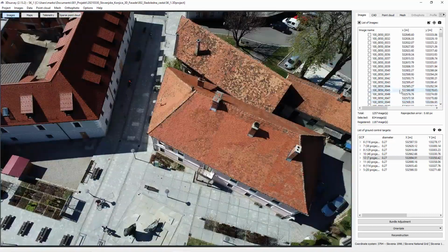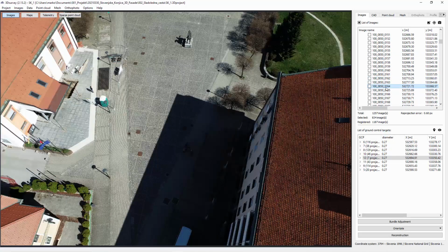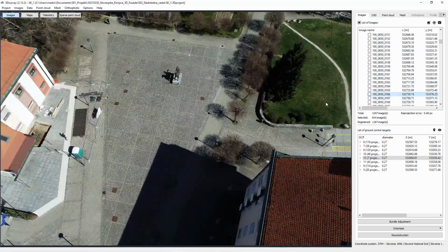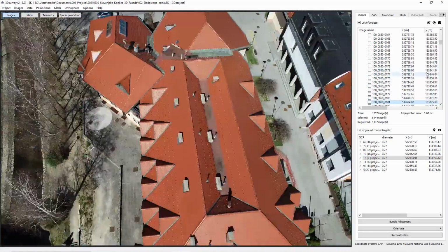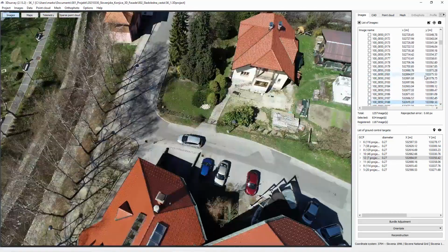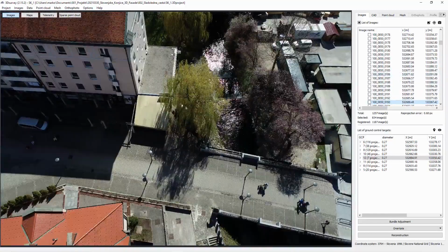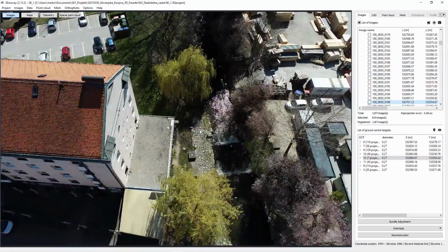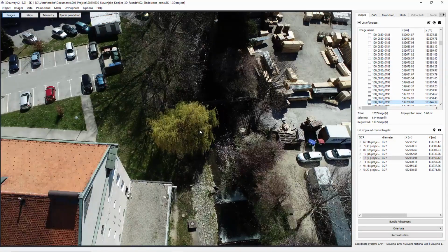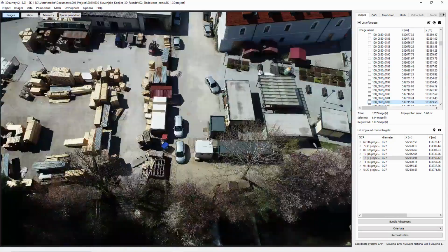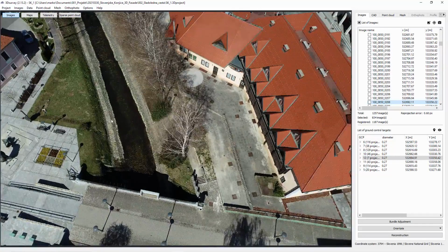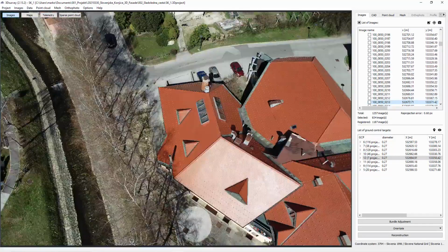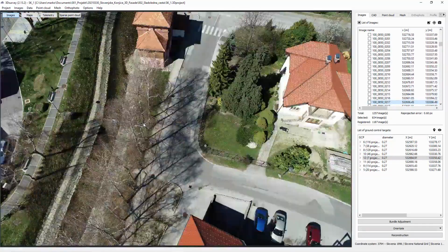Okay, I think we have approximately 200 images with the manual mode, plus the automatic mode with the double grid missions. Here we are still in double grid. Even if I select just the city center of the road, the drone goes and captures a bit wider area, so we have definitely too big an area captured, but nevertheless it's better to have more data than less.